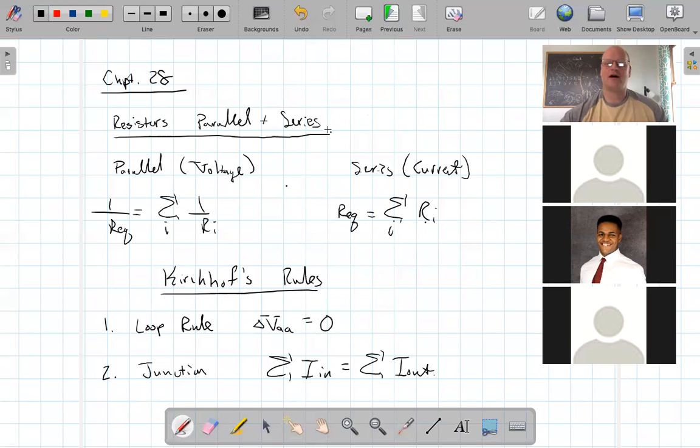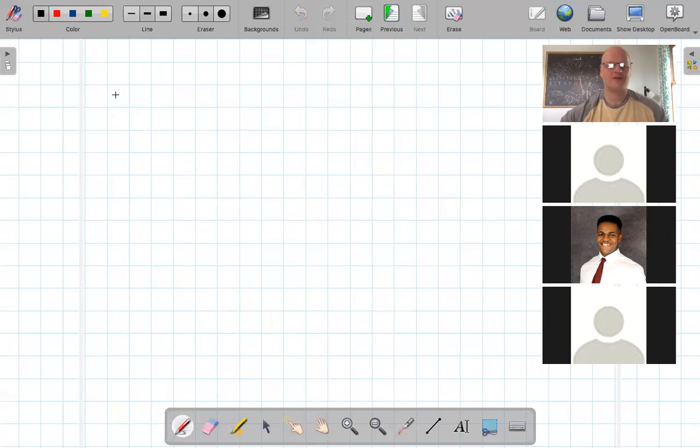Associated with these are a few sign rules. So let's talk about the sign rules here. Our first sign rule is for, let's say, batteries. Do the opposite of usual. So for batteries, here's the negative plate, here's the positive plate. So negative, positive, EMF. And this is, say, point A, and this is point B. Then the change of potential going from A to B is equal to positive EMF.